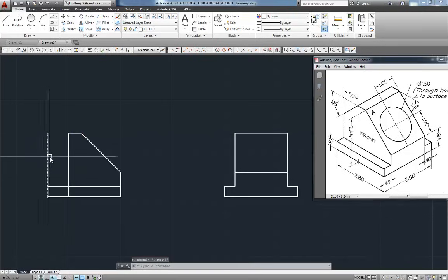And then we go downhill at 45, so we're going to do a line from here. We want to go 180, that's straight to the left, and then counterclockwise or plus another 45. So we want to go angle 225, like so. Angle 225. Click that in. We'll fillet that corner. All right, we'll delete that.